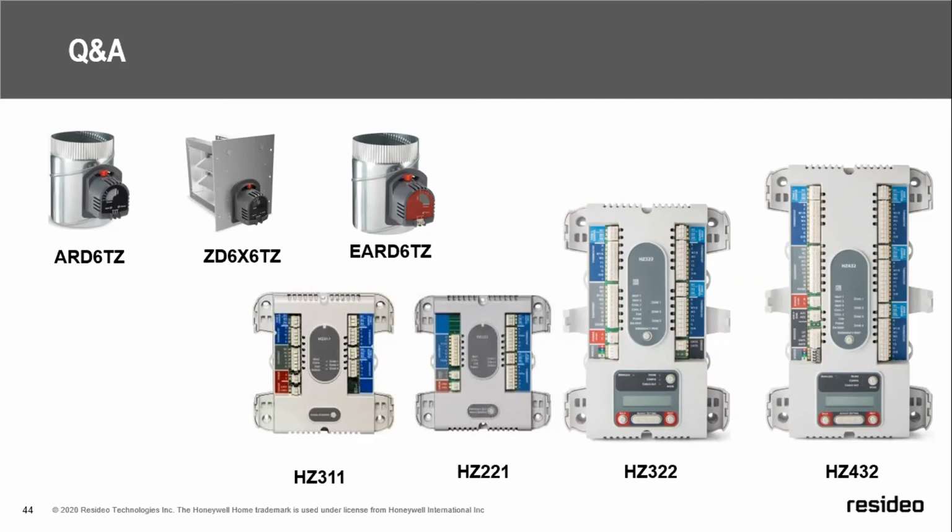So on our steam humidifier as well as our bypass humidifiers, we have the ability to start the humidifier operating, and by utilizing an isolation relay that's in the circuitry, turn on the blower of the HVAC system without the zoning board having any clue whatsoever anything's going on with the G circuit. You say, well, gee, Rod, why are you so excited about that?